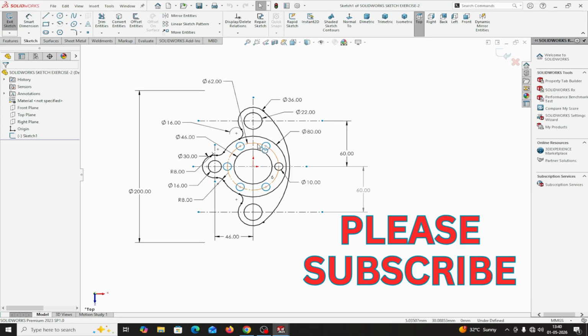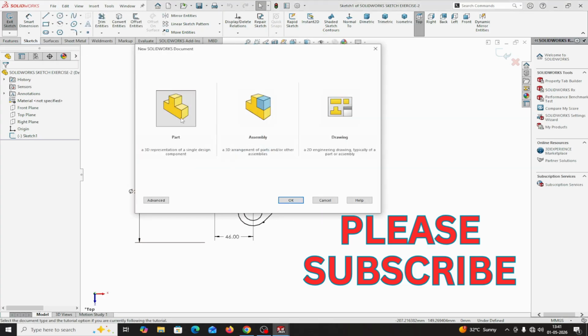This one is 62 mm dia. This is 46 mm dia. And this is the circular pattern of these circles, of dia 10 mm, 6 number of patterns. Okay, I will start from the middle portion. Now file, new, part.